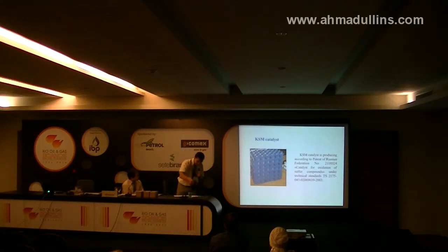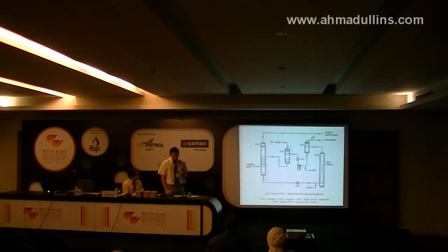For this purpose, we have developed a polymer-based catalyst that is produced in the form of packed elements with an exposed surface. The active components of the catalyst are solidly supported on polymer, which excludes them from dissolving in the circulating alkaline solution and from the formation of disulfides outside the regenerator. Using this catalyst, we have developed the process for liquefied gas purification, see figure 2,